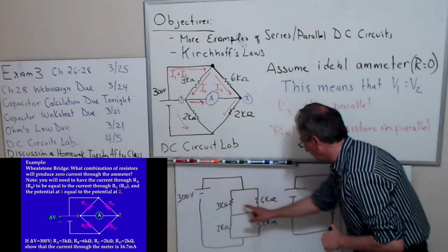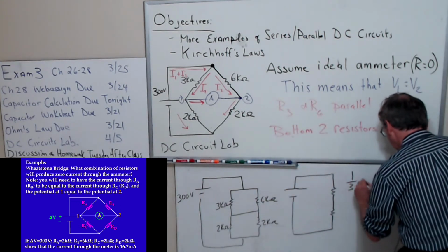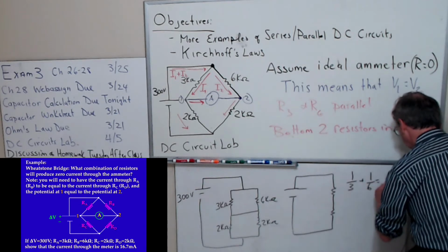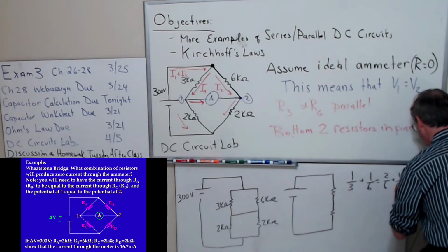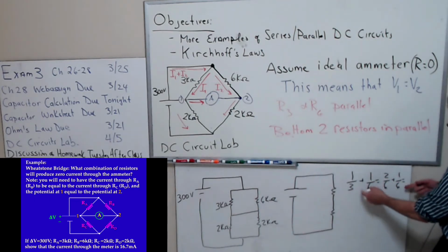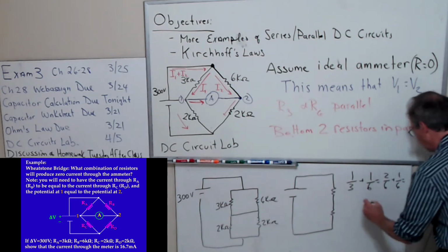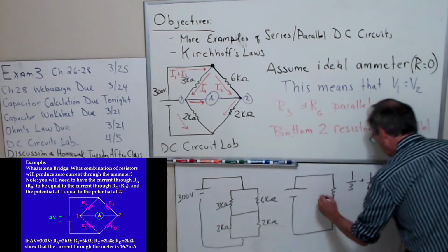What do I get when I combine these two? One-half of an ohm. Okay, you did it quickly. Good. So when you add these up, you get a half, and then you take the reciprocal as what? 2. So this is 2 kilo ohms.